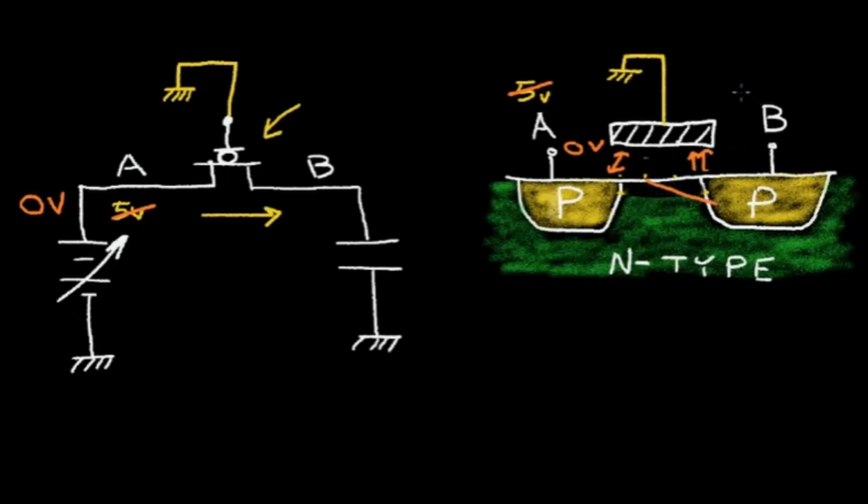But as this B voltage decreases, as it gets to about 0.7 volts, which is approximately equal to the threshold voltage of this PMOS transistor, at that point, at 0.7 volts at point B, this electric field will diminish to the point where the channel region is non-existent. We don't have enough electric field to form the channel and conduction stops.